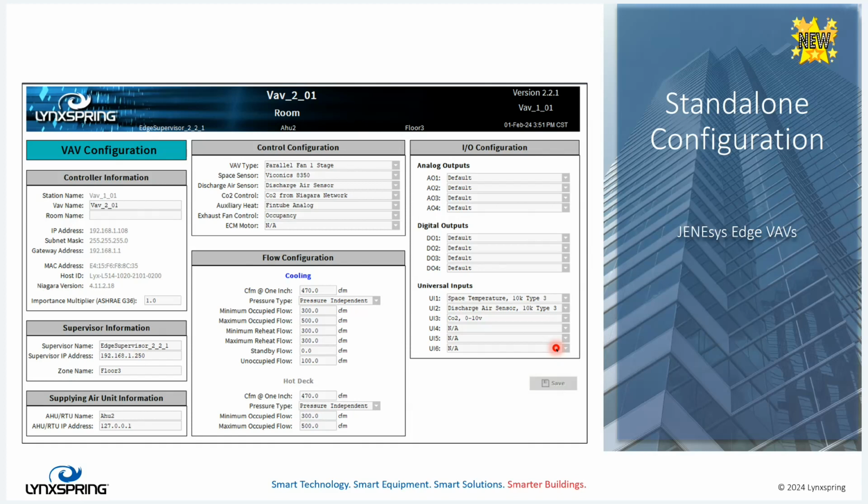It is per VAV. It is designed to pretty much follow the configuration tool closely, but it allows you to set all your settings, hit the save button, and you're done. Now, once you have all your VAVs installed and once you have your supervisor installed, you can still run the rapid integration tool that will build out the structure of the supervisor.